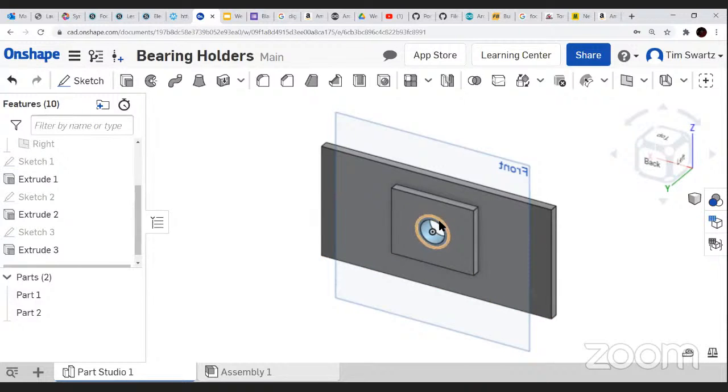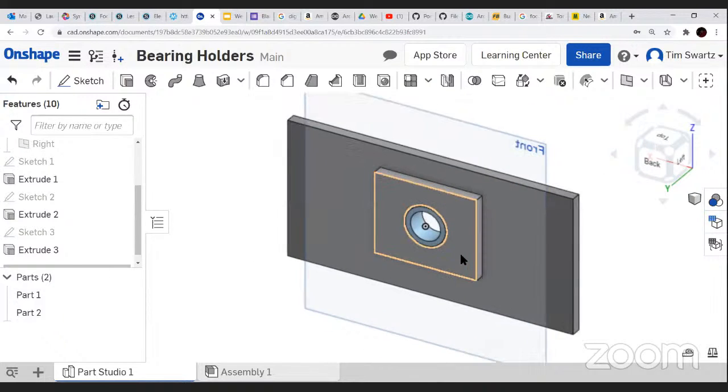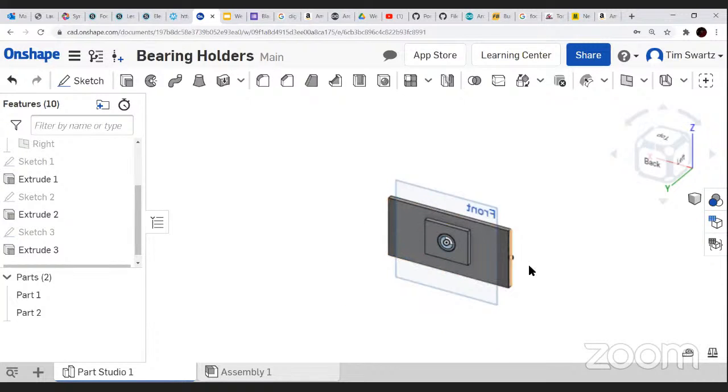It can be done in certain applications, but the other thing we have to think about is that we've got this sheet that is probably going to go about 4 feet. And every time you weld, you're going to have some distortion. When you're trying to align bearings, you really don't want any sort of distortion.